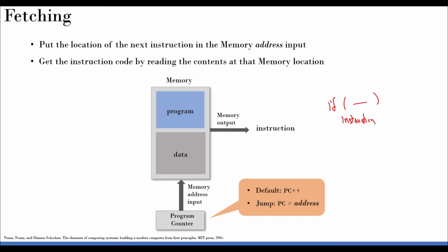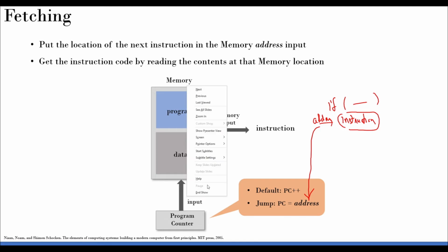So if this is satisfied, you have to execute these set of instructions. So there is an address here, right? So that is what I meant here. If a branch operation is triggered, then the program counter should not be incrementing by 1 and storing the next address, because I don't want to execute that instruction. I want to execute a certain fixed set of instructions, and it will have a memory, and that address should come to the program counter. So we will understand how that will happen.